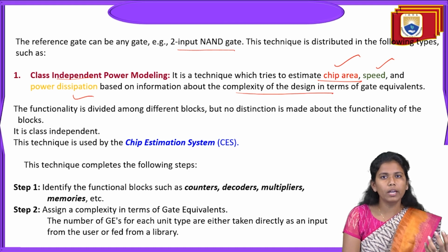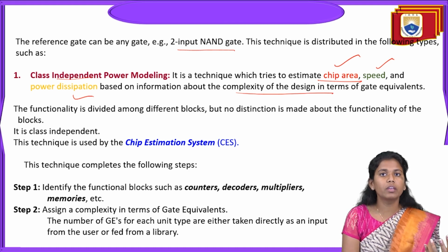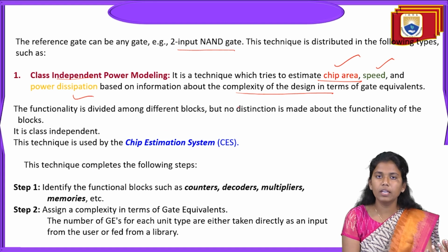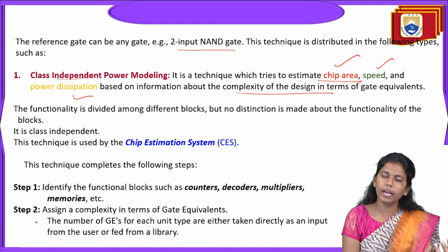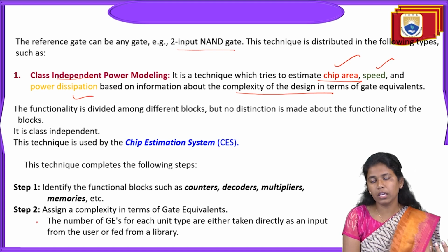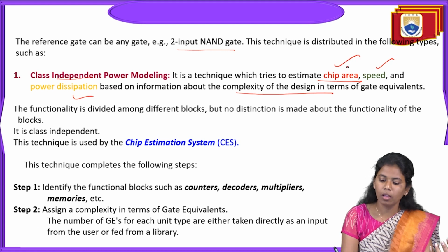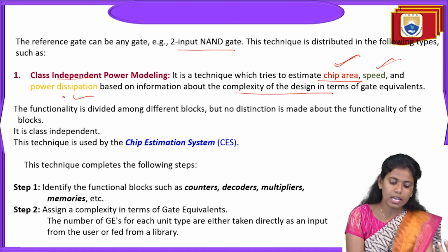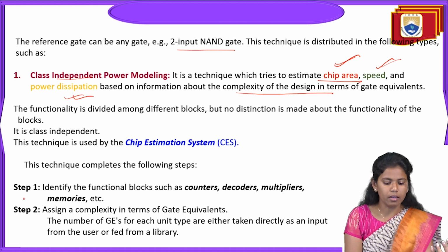So it totally depends on the complexity of the gates. Complexity of the design in terms of gate equivalence. So if the design is more complicated, then we can estimate the power distribution among the chip area, speed of the module as well as the power dissipation. And then the functionality is divided among different blocks.